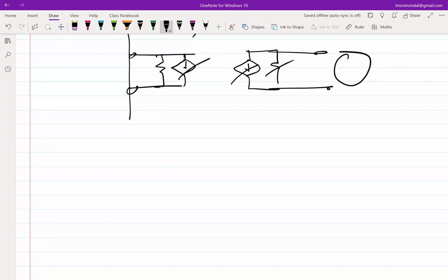Another thing that you can do, it's not a part of the assignment, is to model the effects that we have talked about in the class with a long line. Just put a transmission line of arbitrary length in simulation, and then see what happens to the impedances or to the voltage swings, or even to the stability of a circuit. You can take one of the stable circuits that you might have designed in 610 or 613, put long transmission lines and open circuit the output side and see what happens.